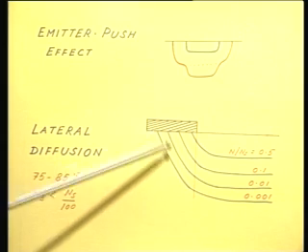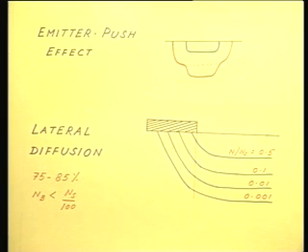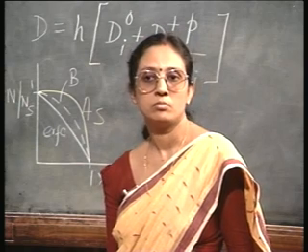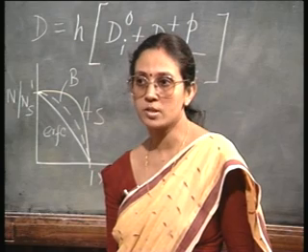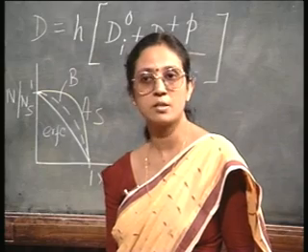Notice that the lines are progressively moving under the oxide window. Now, in a practical situation, your substrate doping concentration will probably be, say, at least 100 times less than your surface doping concentration. Background doping concentration will be at least 100 times less.